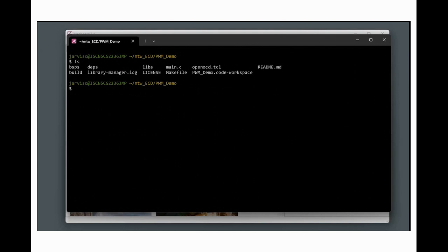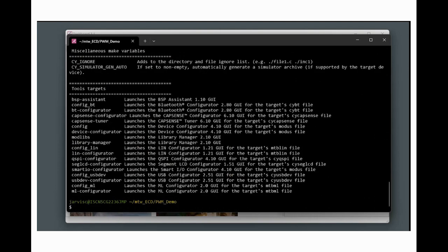In fact, the command line itself is quite a powerful way to use ModusToolbox. It allows you to integrate it into automation, continuous integration systems, or build systems, source code repositories. There's so much you can do when you have access to a build system that is able to facilitate command line. And all of this is based on effectively a make-based build system. So just typing in make help, we see we got tons of details about how I can use it. I've got access to integrating this into continuous integration or building it.